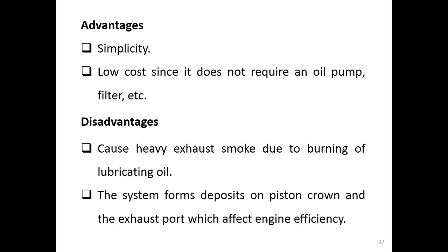If it happens, it can affect the engine efficiency. Because we learned from emissions, deposits sometimes absorb the hydrocarbon, sometimes dissolve the hydrocarbon. So if we have deposits on the piston crown, we may have some hydrocarbon left unburned, and it will come out with the exhaust.